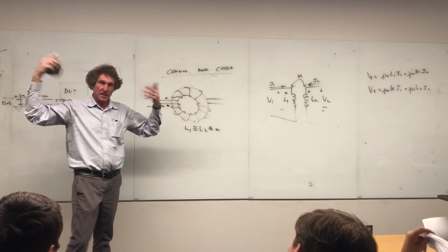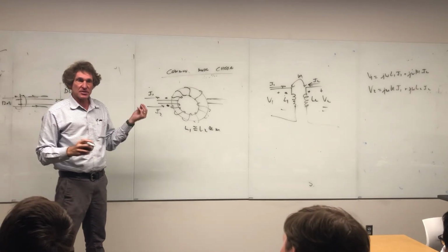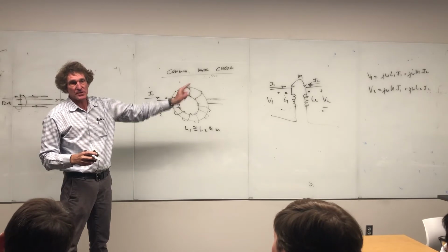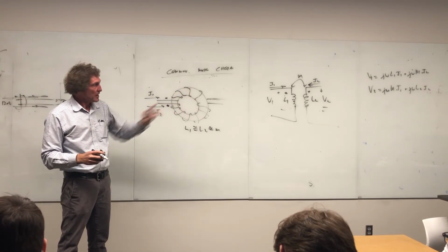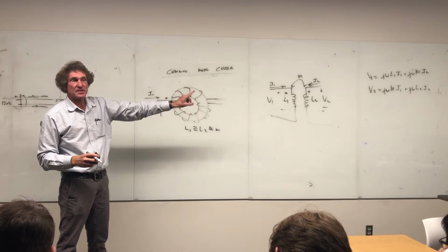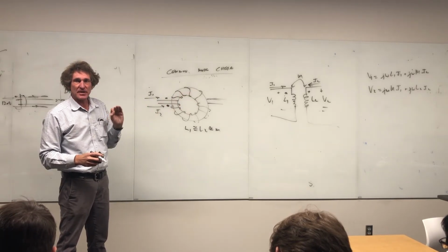You know what an inductor is, usually just a coil. The dot just indicates the sign convention where you assume current into that will cause a plus to minus voltage as shown, V1. On the secondary, current into that dot causes a voltage plus to minus as shown. I'm surprised you didn't get transformers in circuits.